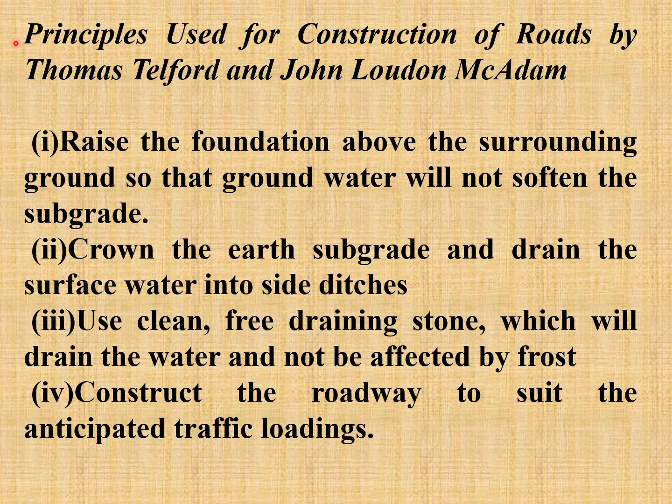Principles used for construction of roads by Thomas Telford and John Loudon Macadam. Well, these principles are very important and still are being followed. Number one, raise the foundation above the surrounding ground so that groundwater will not soften the subgrade. Subgrade is the natural soil in most of the cases, and it acts like the foundation of the road. Number two, crown the earth's subgrade and drain the surface water into two sides.